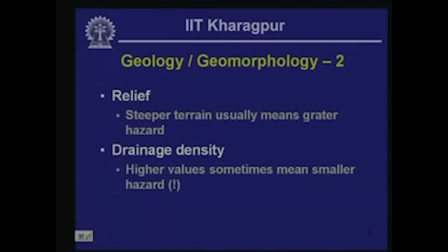Of course, I should have a rejoinder here at this particular point, because steeper terrain could also mean that the soil or rock unit underlying that slope is stronger and more resistant to weathering, and that in some cases could mean that you are going to have less frequent landslides in steeper terrain, because steeper terrain itself could be an artifact of strong or sound rock or